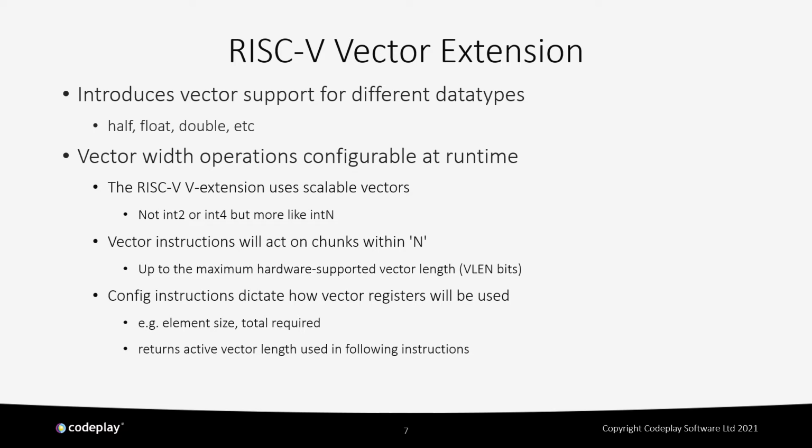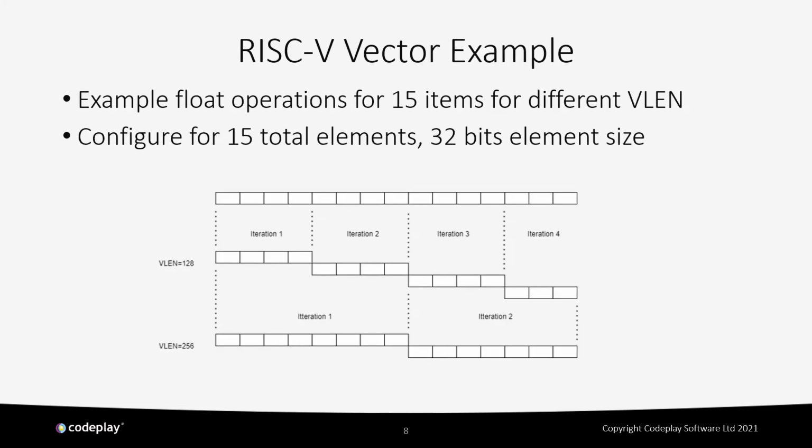This extension is key for us as we want to accelerate using this extension. This extension can simplify vectoring across an unknown number of items at compile time, allowing the removal of scalar tail loops using predication. Also, multiple registers can be combined together to much larger vector types. Let's look at an example to better understand the RISC-V vector extension.